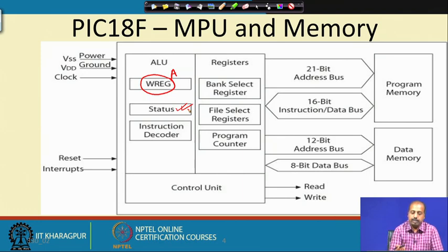As you can understand now what is going to happen, the instructions first come to this instruction decoder. The instruction decoder will control all other modules that are there, and then we have this memory select register. They will select the register from where the data has to be brought, and do some operation with the W register as one of the sources and also the destination. Then from the W register you can move the values to other registers and so on. We will see some examples later.